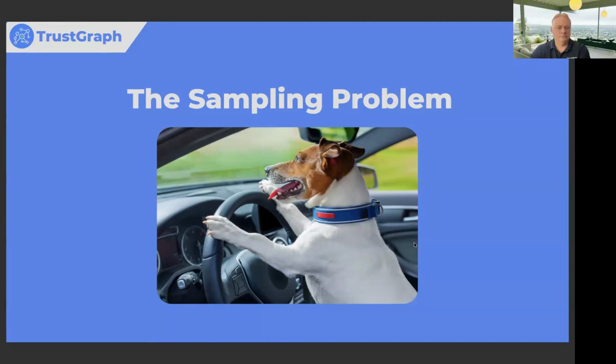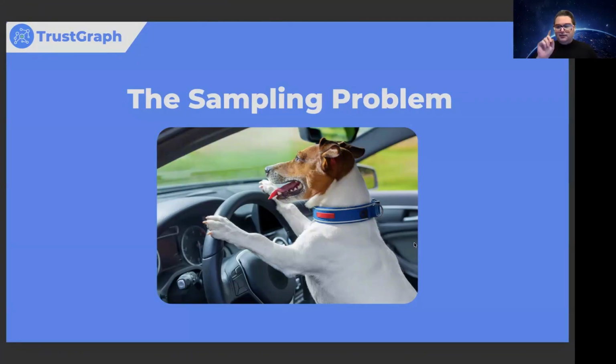And as a matter of fact, we even found some MCP servers that will connect to CAN, sort of. It's simulated, but you could actually connect it to CAN. So if you had a vehicle with a CAN bus, you could actually use AI to tell me what's the steering angle. And you would get an answer, and you would think, amazing. There's only one problem. If you look at that actual CAN bus, this is constant. This is just a flood of data being updated every few microseconds.